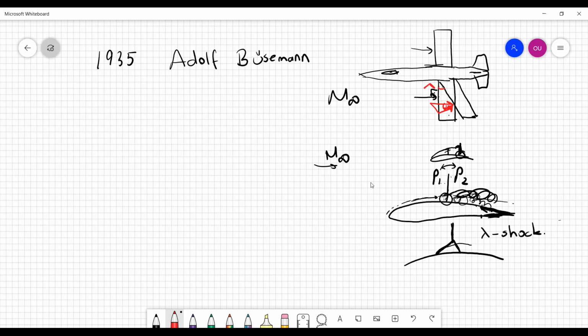Even if this perpendicular component is supersonic, it will be less than your actual flight Mach number. So your drag critical Mach number and drag divergence Mach number will be pushed to higher levels, first of all. And even if the M infinity is very high, close to supersonic, let's say high transonic, the flow over your wing with a properly swept wing could still be like subsonic flight.